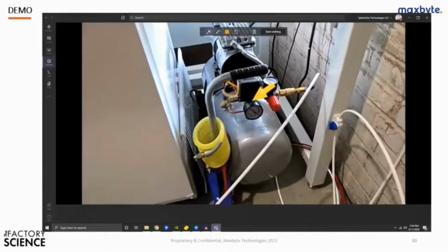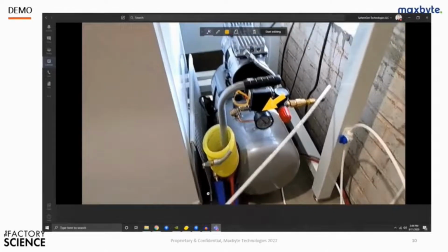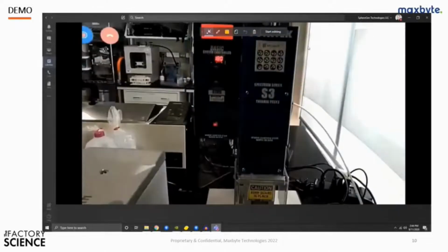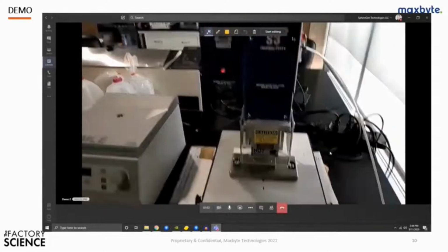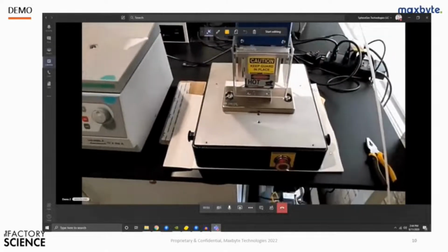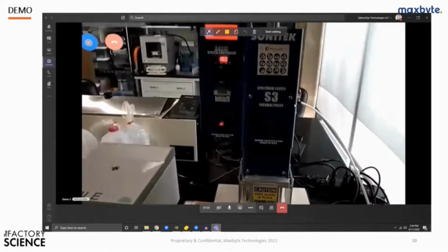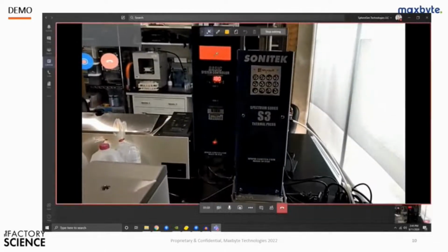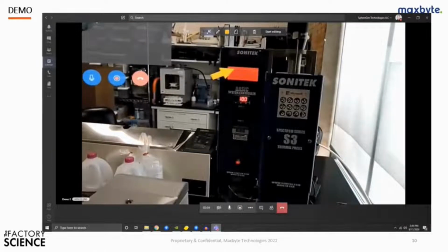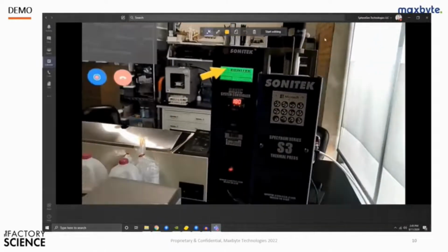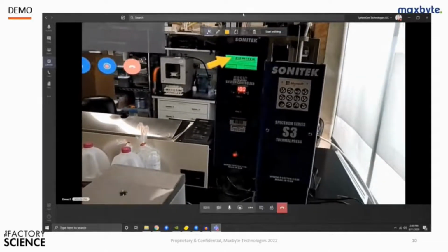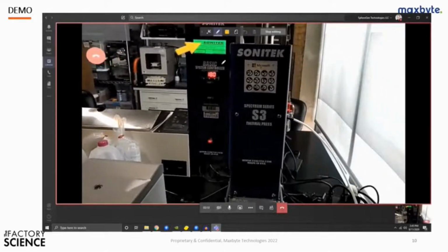So now if we go back up to the Sonatech. Okay. Great. We're going to want to make sure that initial knob's pressed in. The emergency stop? Yeah, okay, it's been reset. Excellent. Now if you can pay attention to the reset button right here on this LCD screen, you're going to press that button. Oh, so it's a touch screen. I missed that. Okay, beautiful. Cool. And I can see here that you are at the right operating temperature. We know we want to be at 180 degrees or above.